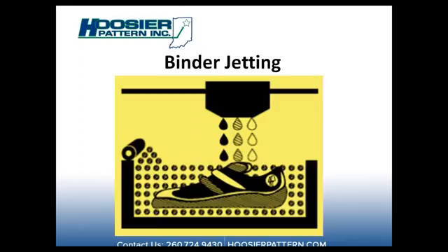This is what we use extensively with our sand. It is an additive process where a liquid bonding agent is selectively applied onto a thin powder material layer by layer. These binders can be organics or inorganics. If a metal powder is printed, they are typically fired in a furnace after they are printed. If ceramics are printed, then the end use will determine if the part needs to be fired or not.